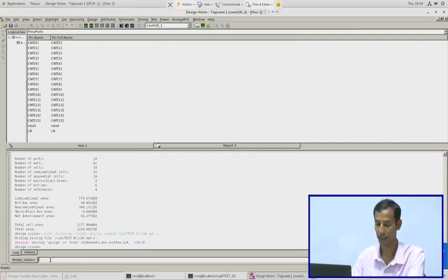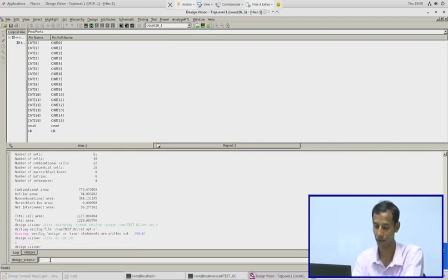And another thing is that we have to write the corresponding design constraint file which we have used here to obtain the netlist file. So how to do that? You just write this command, write_sdc, with the name count.sdc file. Okay, so these things we have done.